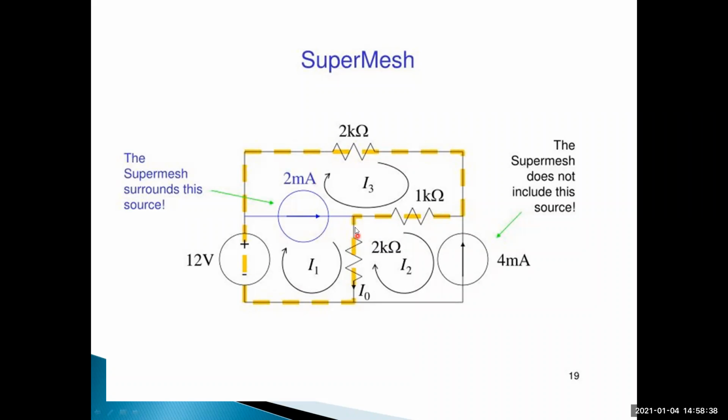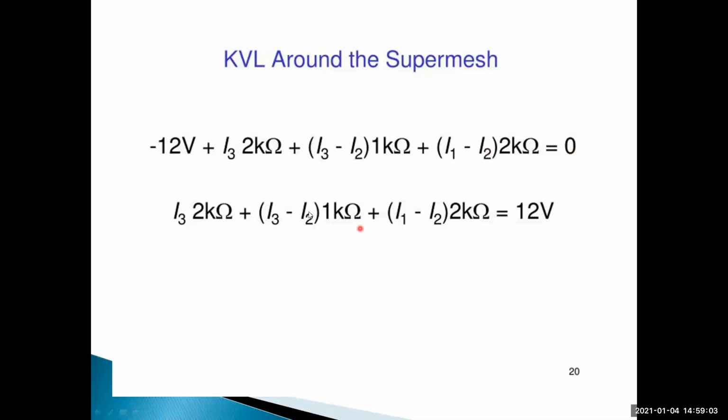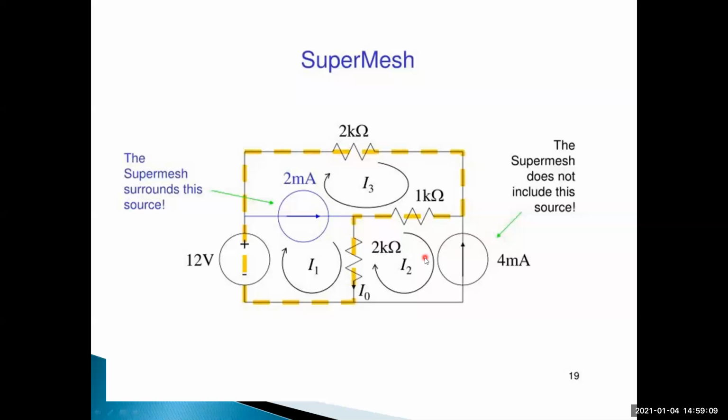And then coming here, I'm going in the clockwise direction. In this direction, what is the current? I1 is entering like this. I1 is higher in magnitude, then only here plus and here minus. I1 in this direction and I2 in the opposite direction. That's why I1 minus I2 into 2K is equal to 0. Then by solving these equations we'll get I1, I2, I3. Substituting I2 is equal to minus 4 milliamps, I1 minus I3 is equal to 2 milliamps, and using the super mesh equation.